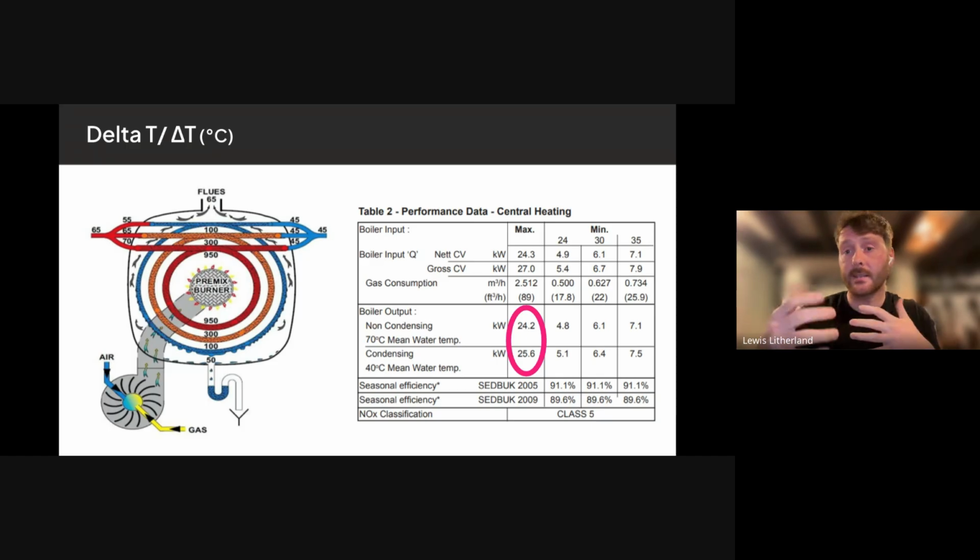And again, this isn't a typo. If you look at any modern gas boiler, their output tables are all exactly the same because they should all be in condensing mode. As I say, once you get into the real world, you realize quite a lot of them aren't. I think they did a study, and the average efficiency of a modern gas boiler is like 80%. It's mad, even though it was sold at an efficiency of 92 or 94 or whatever it says on the box.